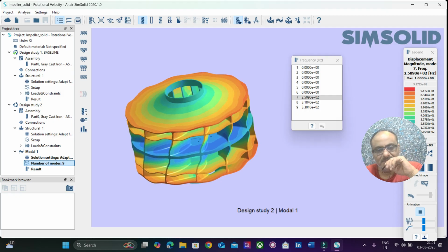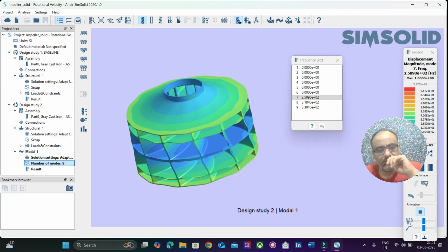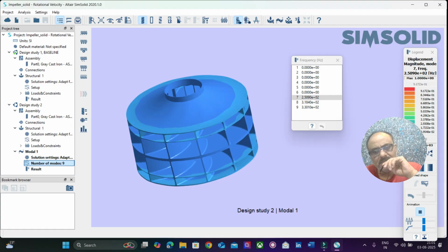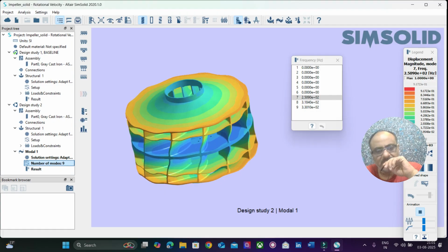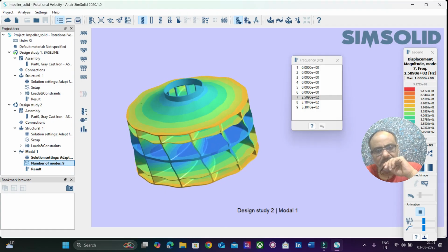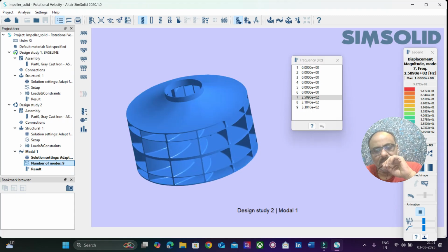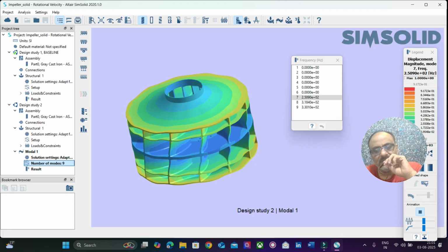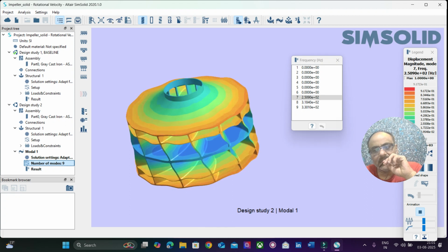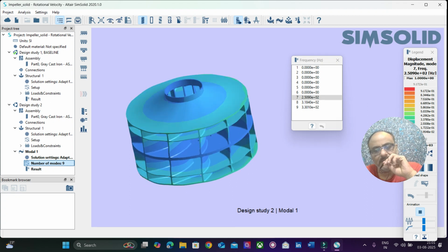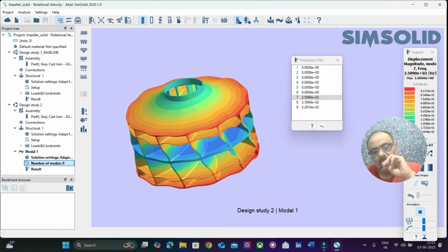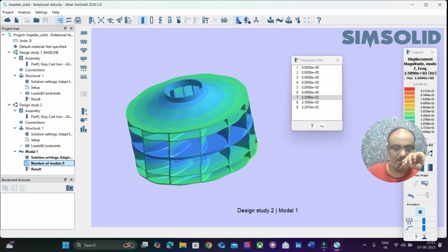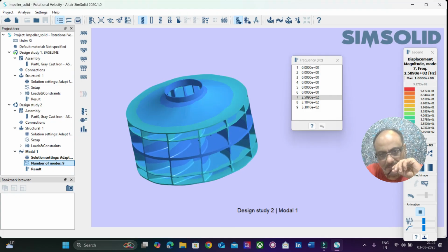Similarly, we also have other test apparatus that help us determine the normal modes or the natural frequency. So here these 3 modes, the 7, 8 and 9, from 250.9 hertz to 330.1, are the first 3 fundamental frequencies of the impeller, the induced draft fan radial impeller.